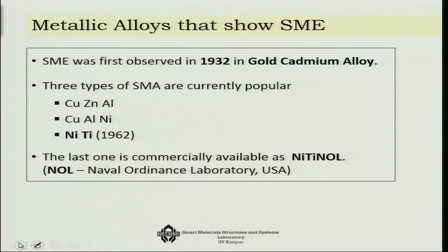There are three types of SMA that are currently popular. One is copper zinc aluminum, another is copper aluminum nickel, and the other one is nickel titanium alloy. So it's a binary alloy in comparison to the other two, and since 1962 when this was discovered, it is becoming more and more popular.